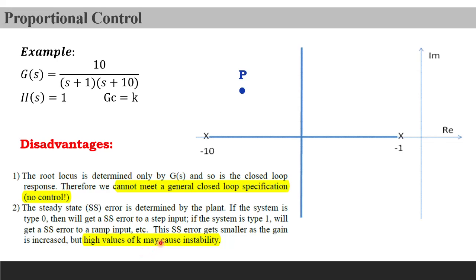And by saying all this, we can conclude that this steady state error gets smaller as the gain is increased, right? So you want to increase the value of gain so that the error reduces. If you remember, the value of this k was inversely proportional to the error, so you want to make this value as high as possible to reduce the error. But simultaneously, we have already discussed that higher values of k may induce instability in the system, which might not be a viable case.